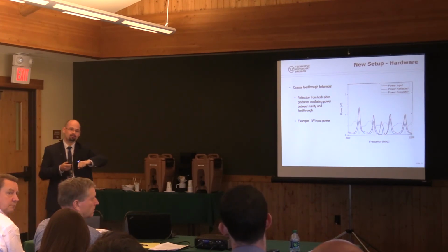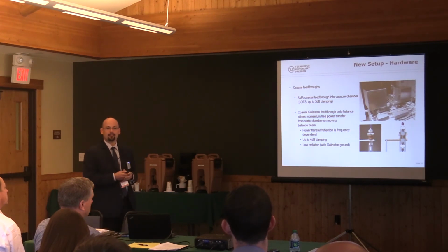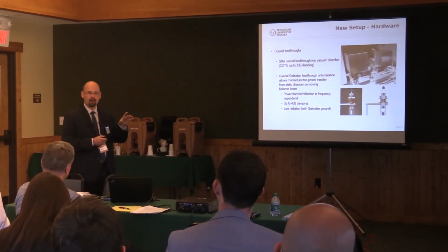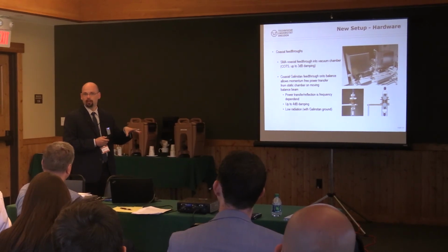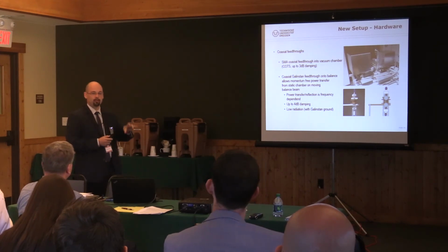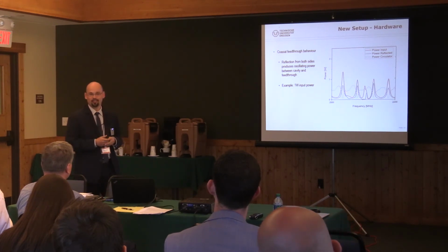Actually, one other question about your previous slide. Do you have an SMA feed-through to the vacuum chamber? Yes, they're quite physically small. Do you have problems putting that much power through that small of a center? The power for SMA is about 100 watts, and N-type connectors are rated for 150, I think. So the problem is not the real maximal power of the SMA feed-through, but more really with strange behavior I will come to later.